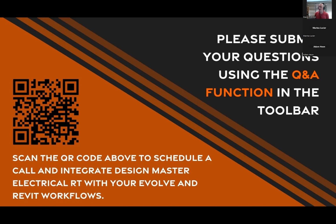Another question from Benjamin. If the engineer didn't create his one line in Revit and link it with Design Master, is there still a way to transfer the data to the contractor? You could. This isn't necessarily what we're envisioning with the workflow, but this export command just depends on the panels being in Revit and being connected in Revit. So it would properly export the connections. Going back to the conduit run schedule here, the start and the finish would be correct, because we would be able to pull that from the Revit model. If you didn't use Design Master, these conduit sizes would not be correct, so you would need to go back and update those to the right value.